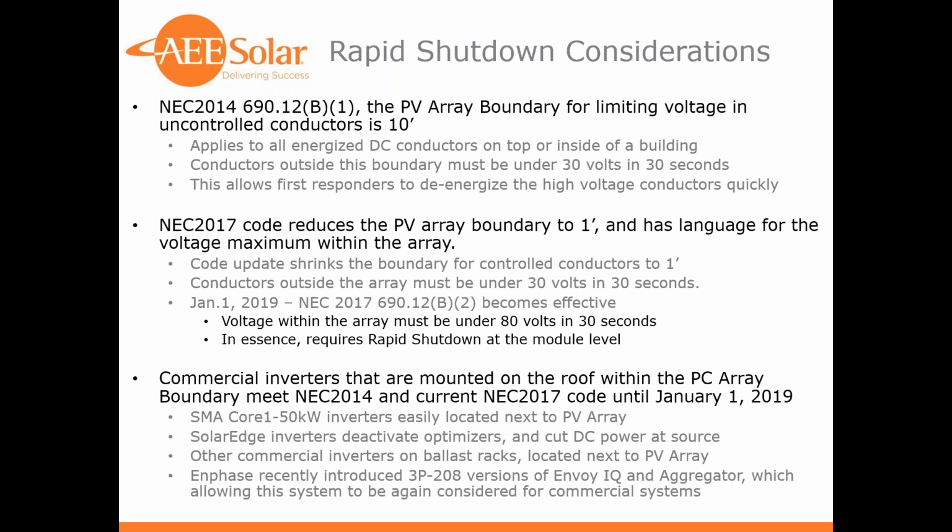A special comment about that: be sure that you install those inverters per your manufacturer's recommendations. We did see some inverters where, being that they are now at a tilt and not mounted vertically, special care has to be taken with the drip boundaries of your conduit to make sure you don't get water intrusion in those inverters. We have seen a couple of inverters where some water intrusion happened in the DC combiners, and that is not good for those inverters.